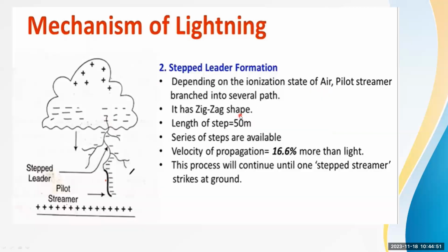Next, coming to the step leader formation. The streamer is formed like tree branches, like steps. This is called step leader formation. Step leader formation depends on the ionization state of air. If the air gets more ionized, then steps are formed in this way.